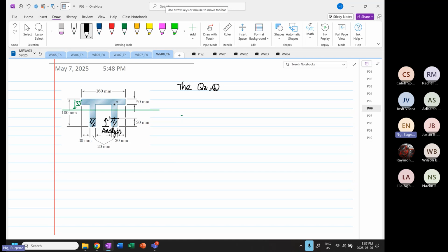Okay, the analysis starts from the furthest distance, start from y max. Okay, so over here, this is our y max, and then it goes inside because this is in fact also our small y, right? Okay, if we look at the analysis starts from y max. So when that's the case, then we can calculate our first moment of area. Okay, so we're going to use this technique. So we know that the distance from here to here is 65. Okay, so we know that QZ